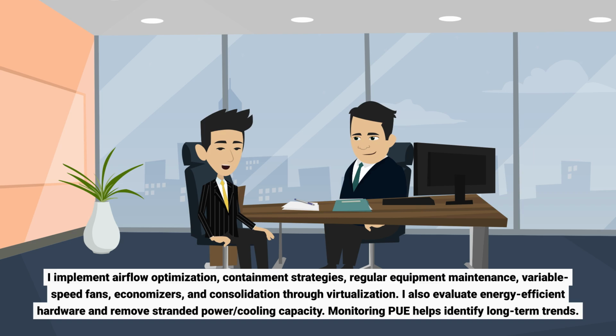I implement airflow optimization, containment strategies, regular equipment maintenance, variable speed fans, economizers, and consolidation through virtualization. I also evaluate energy-efficient hardware and remove stranded power/cooling capacity. Monitoring PUE helps identify long-term trends.